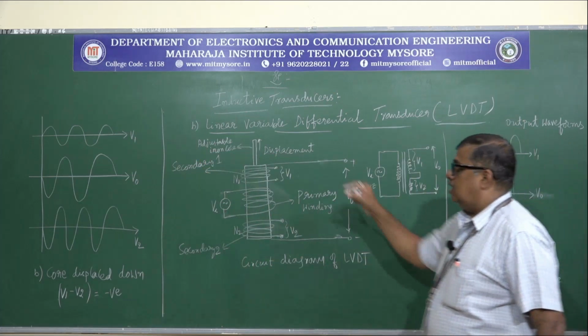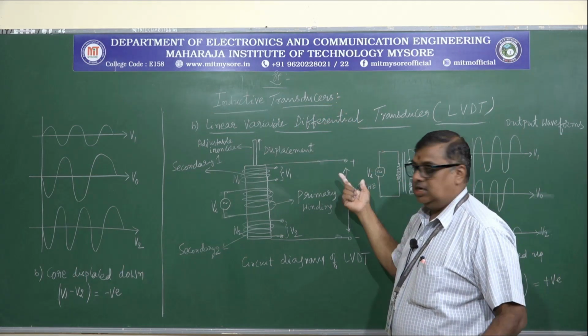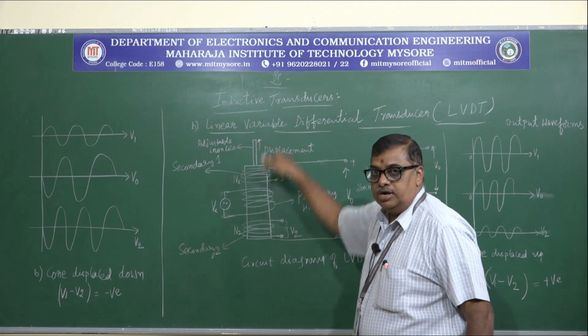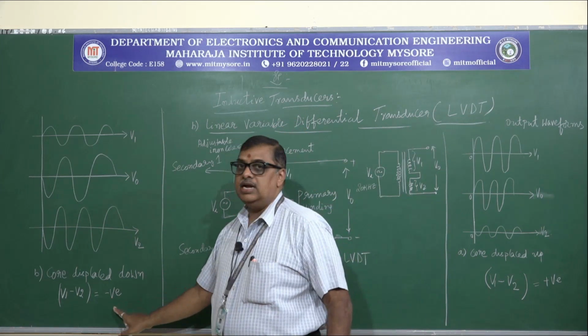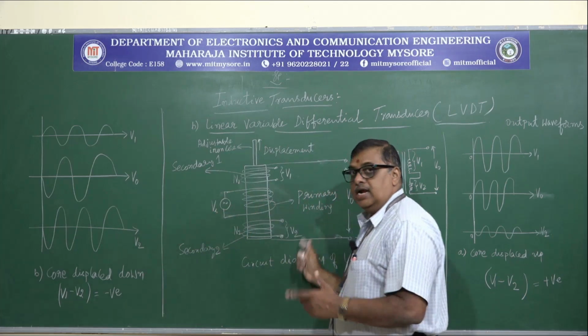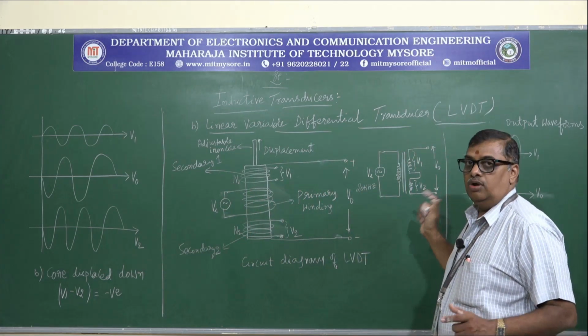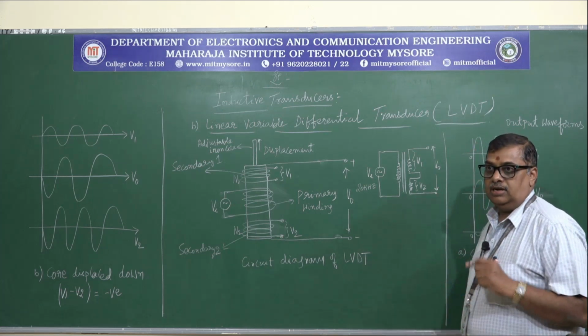That means whenever the core is moved upwards, the displacement is positive. Whenever the core is moved downwards, the displacement is negative. We can measure both positive and negative displacement using this LVDT. So this is one of the types of inductive transducer.